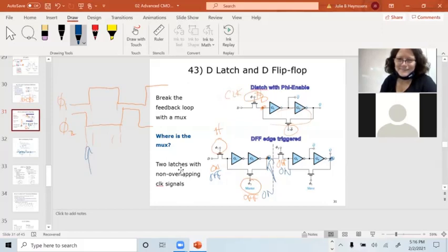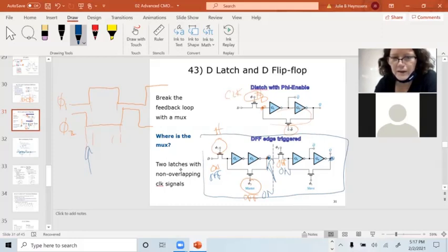So what's going on here? This looks kind of similar to slide 44. It's the same circuit that's on slide 44. That's an edge triggered flip-flop. I've got to add that master slave component in there to get the edge triggered, so I have the delay between the clocks. This right here is just an enable without the master slave.